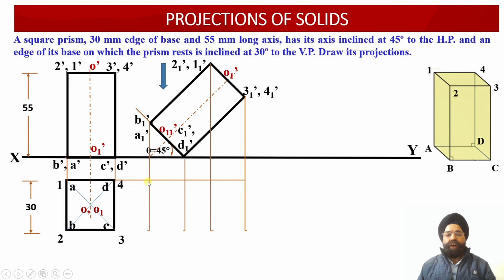So once we draw the first horizontal line, onto this horizontal line 4 points corresponding to the plan projection view will be available. Similarly, here also we have got 4 points lying into the plan projection view which we have already drawn. Now from here, once we draw the horizontal projector line, onto this horizontal projector line we are going to get 4 points into the plan projection view. Let us evaluate those 8 points over here.